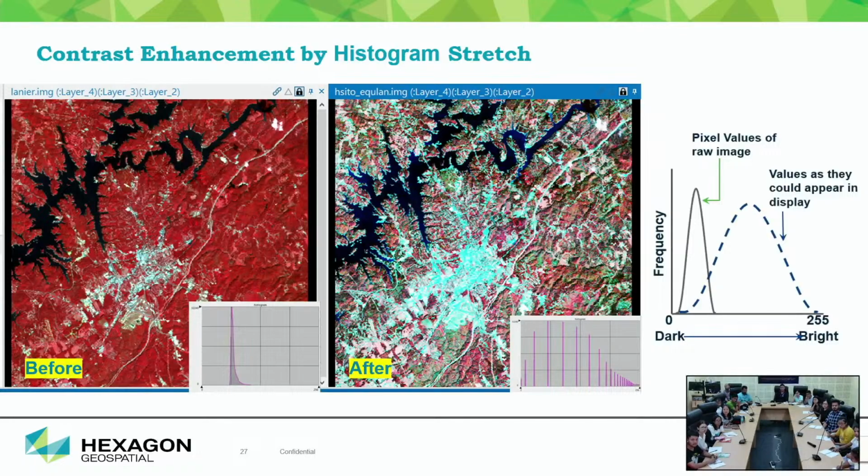Suppose you have satellite data taken in 2008, and when you go for 2009 you can see that some radiometric imbalance is there. So we have to match and correct this imbalance, otherwise we cannot perform the change detection. Maybe some part will be brighter in one image and darker in the second image. So when the computer performs the change detection, it will be unable to extract the information properly. That's why we need to perform histogram matching.